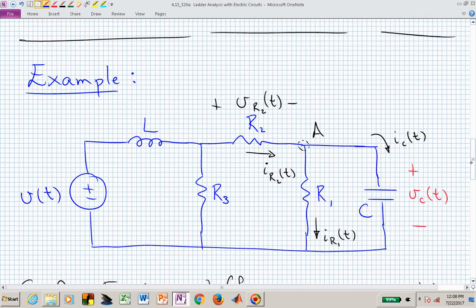What's step 5? Well, now, before we can maybe even obtain this current through R sub 3, we might need to know what this voltage is across R sub 3. But we can find that voltage. That's now just the sum. If we just do this KVL, we now have V sub R sub 3 in terms of V sub R sub 2, which we've already found, and V sub C.